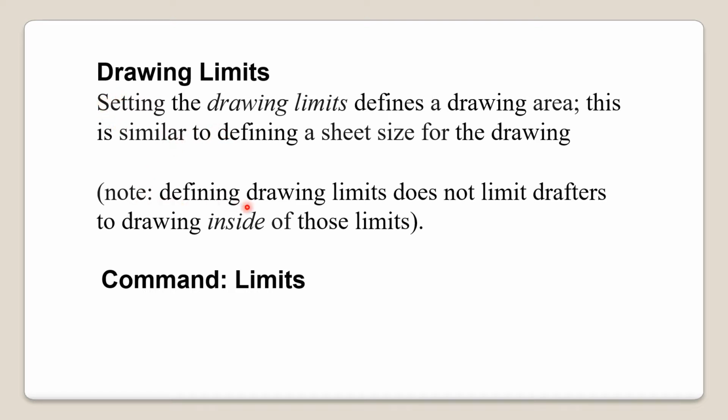Note: defining drawing limits does not mean limiting drafters to drawing inside of these limits. It does not mean that after defining the limits we are restricted to work only within these limits. We can go beyond that. And the command for drawing limits is LIMITS.